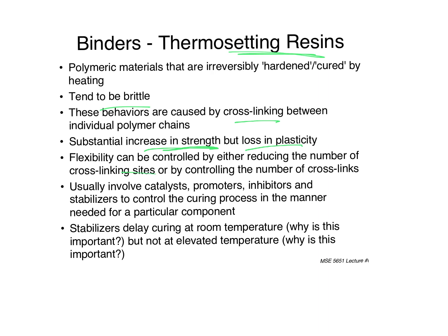And you can change this by filling around the structures and either inhibit or promote the reaction between these different parts. And you can delay curing at room temperature so that it stays strong. But at elevated temperature, you can cause curing to occur, which is where you want it to become strong after it's already inside the furnace, which is kind of a neat thing if you can make it happen.